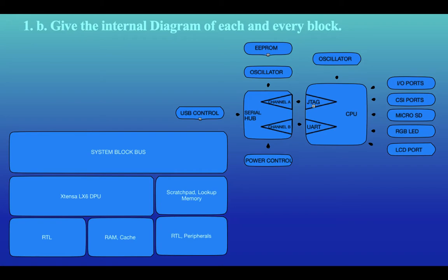Inside Tensilica's complex system on chips, you can find many different processors from general purpose processors to function specific offload engines that add programmability and flexibility. Although general purpose embedded processors can handle most of the control tasks well, they lack the bandwidth needed to perform complex data processing tasks. Xtensa LX6 DPUs are configurable and extensible and ideal for handling complex compute, extensive digital signal processing applications, where a register transfer level RTL implementation may be the only other option.